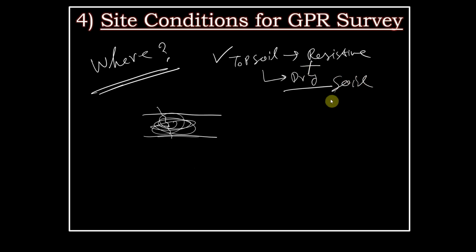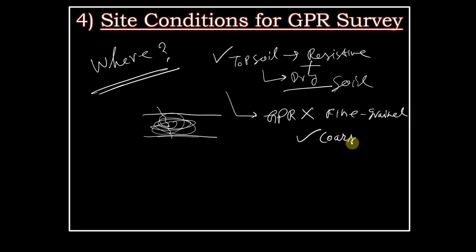Okay, the second criterion is that GPR does not work in fine grained soil. GPR works in coarse grained soil. So if you are seeing that your top cover is kind of coarse grained, then you should go for a GPR survey. And if you see that this top layer is made up of clay, then you should avoid it.